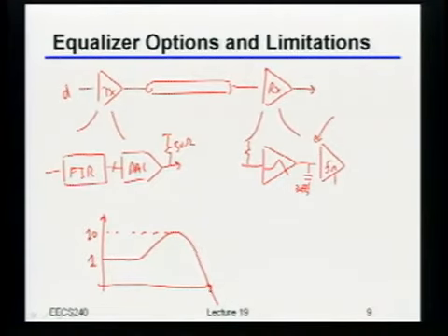Okay? So now, let's say that I tell you the peak-to-peak swing I can put out of my transmitter is 200 millivolts. Okay? So now, here's the interesting question, the thing I want to use to point out. If my peak-to-peak swing is 200 millivolts, and I can't go more than that because, let's say, something in my DAC comes out of saturation, what does that mean these levels here will actually translate into in terms of millivolts?